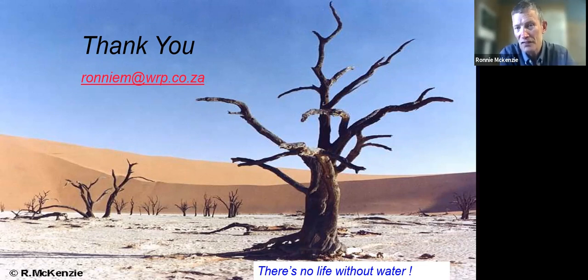And if there's a fire, the fire brigade will come, or if there's a burst pipe, they'll shut off 10 valves to isolate an area, and then they'll open 6 of them and go home, and you find your pressure zones now all over the place.